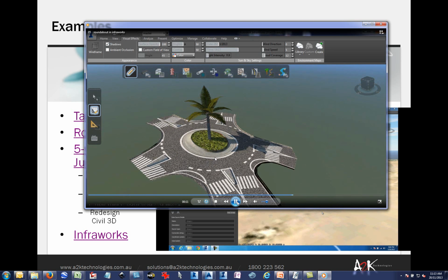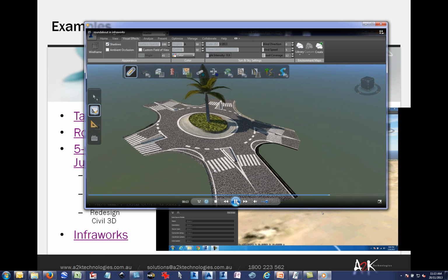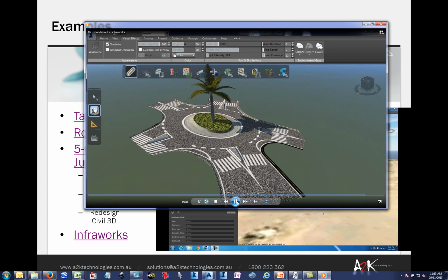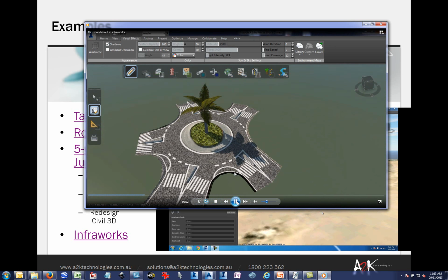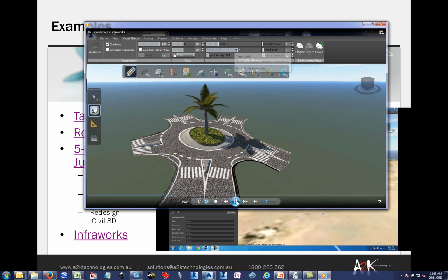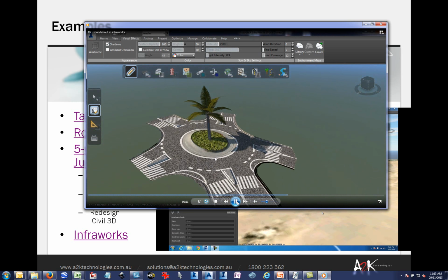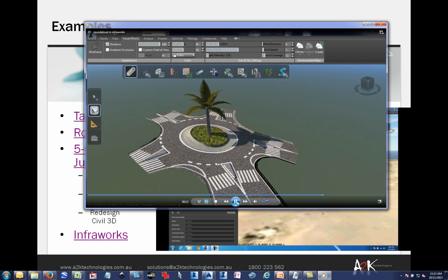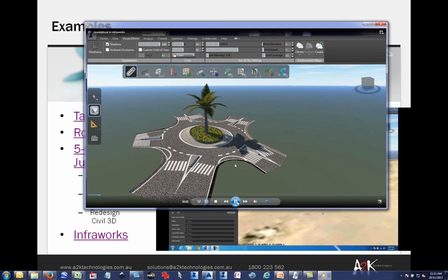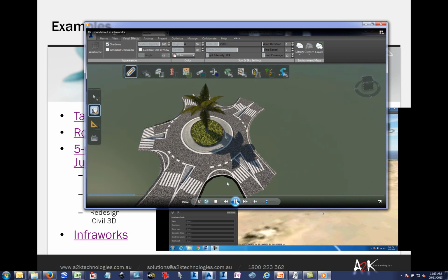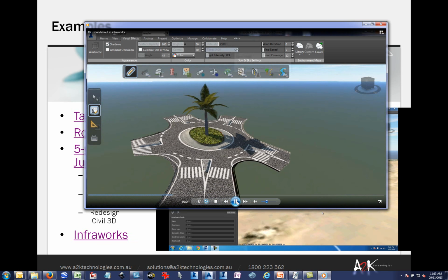What you can also do is put this onto your iPad and walk on site and see how this will look using augmented reality. All you do is hold the iPad up, turn on the camera view, and leave the GPS and orientation to position the angles properly. The part you have to be careful with is that the GPS of the iPad is not that accurate, so you may need something else to improve that. Once you get that in place, you can show exactly how this will look on site.